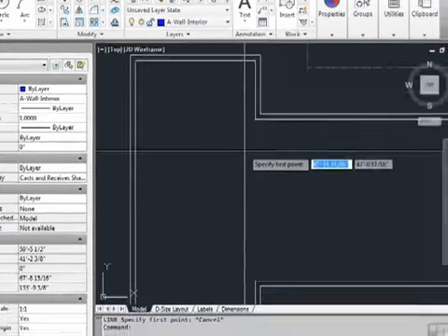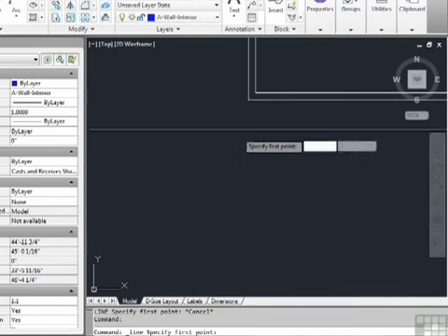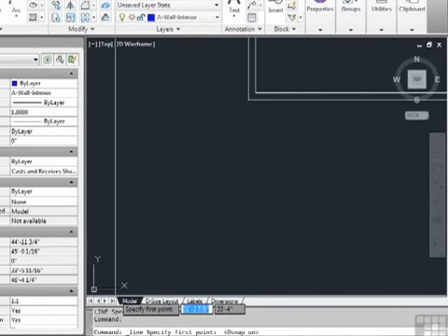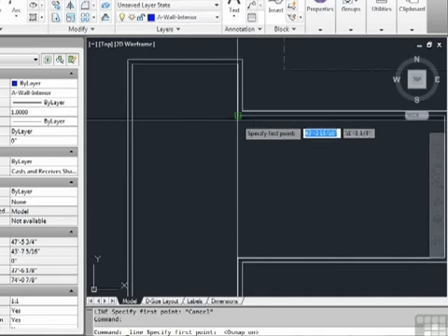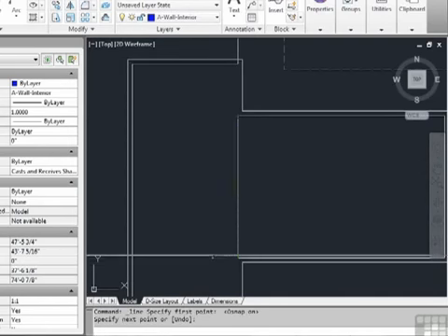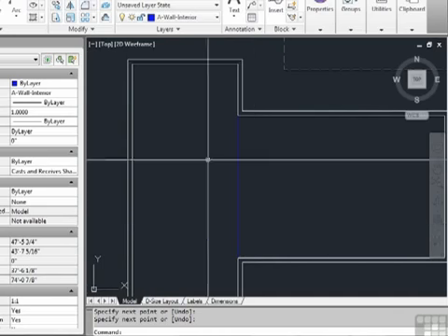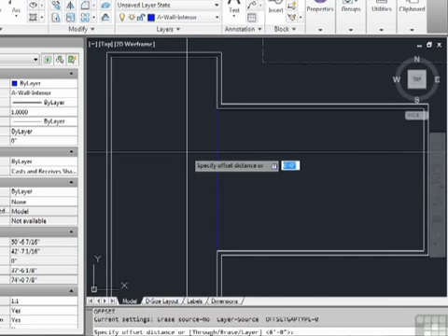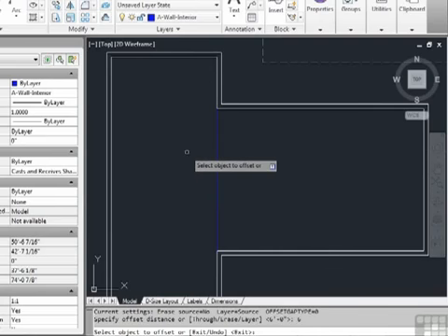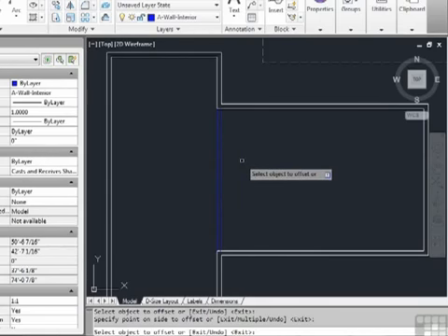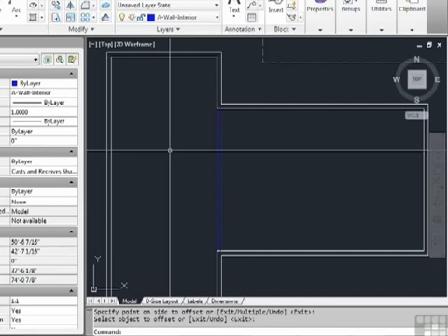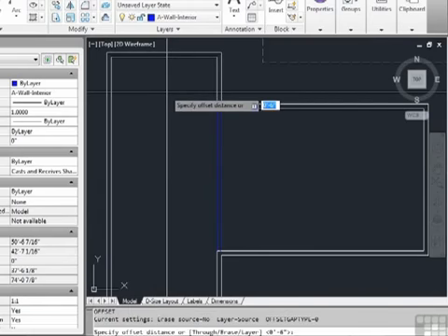and we're going to draw our wall from this point. Turn on our O-snaps. You can also press the F3 button. Pick a point, pick another point, enter. Offset this wall 6 inches. You don't need to put your apostrophe or your inch mark. You can just type in 6, and since inches is our standard unit, we'll be able to draw directly to 6 units, which is 6 inches. Now we need another wall that comes out about here. It's 12 feet down from the inside.